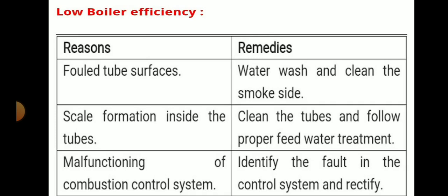Low boiler efficiency. Low boiler efficiency is mainly caused by fouled tube surface, scale formation inside the tubes, and malfunctioning of the combustion control system. If there is fouled tube surface, you can do a water wash and clean the smoke side.